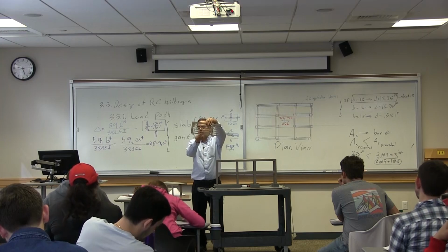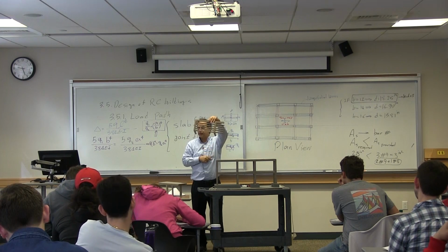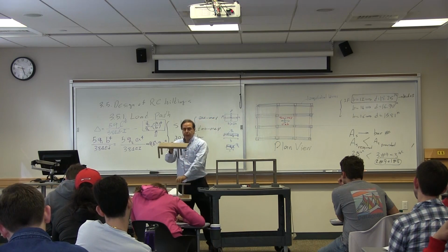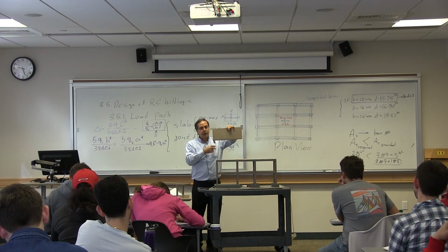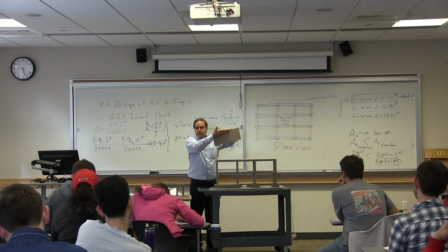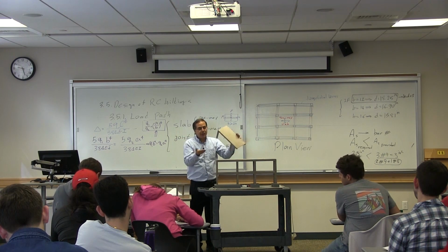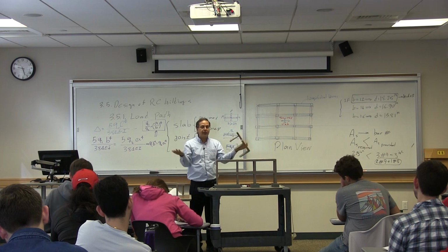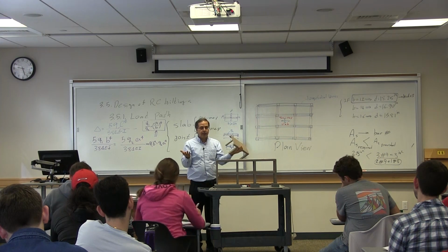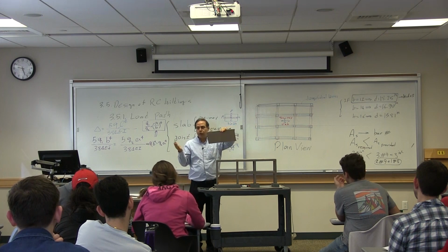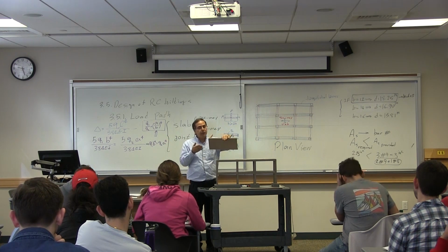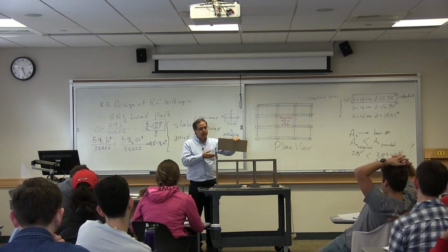Because the joists are carried by shorter beams. If I choose this floor system, the load goes to this beam and to this beam. Obviously, the design of those 2 structures are very different. Therefore, if you don't know where the loads go, you would not be able to design the structure properly.